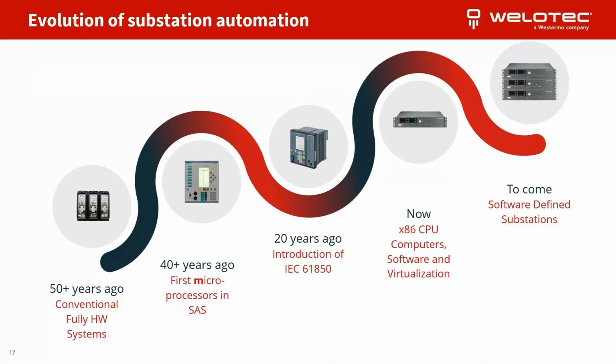But essentially, the standard provided interoperability among hardware devices. This means we can now bring substation functions and applications to standardized computing hardware and take advantage of the different type 1 and type 2 hypervisors that Ryan just discussed. So what we see today are certain components or substation functions, such as firewalls, gateways, RTUs, or protection relays, being moved to a standardized compute platform, but it is mostly type 1 that we're seeing today, where you have a single server running an application with its operating system specific to that function.